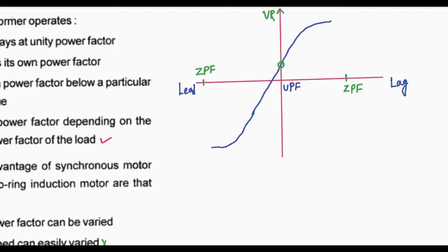And this is a very important plot you have to remember. I have told many times this plot should be remembered not only for the transformer but also for the transmission line voltage regulation and also for the synchronous generator or alternator. This is the same voltage regulation curve we have to remember. That means for a lagging load the voltage regulation is always positive, and for a leading power factor load, the voltage regulation may be positive, may be zero, may be negative.